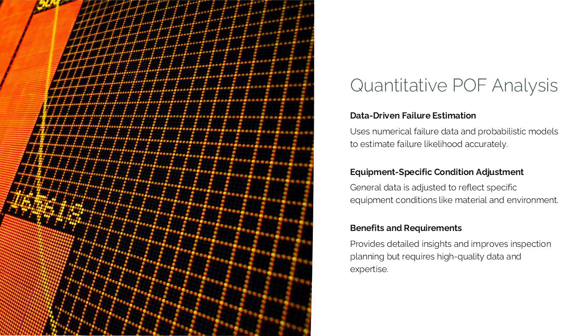This slide explains that quantitative analysis can provide more detailed insights, including time-dependent failure probabilities and uncertainty ranges. However, it also requires higher quality data, greater technical expertise, and careful validation of assumptions. When applied appropriately, quantitative POF supports more precise inspection optimization and long-term integrity planning.